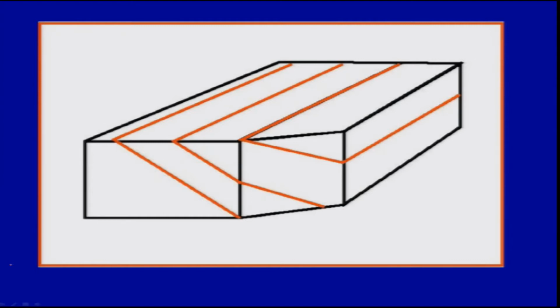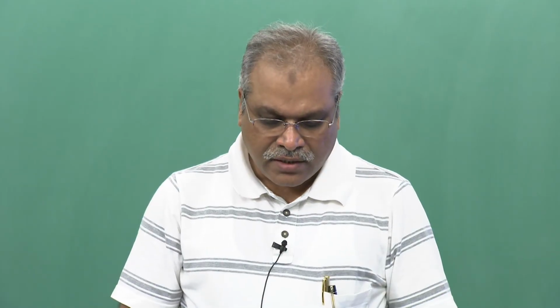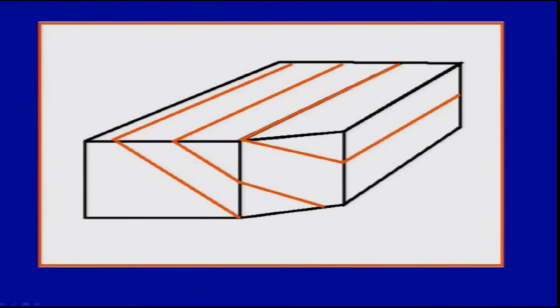If you come across any inclined or dipping strata or beds, it is extremely important to know and understand which face you are looking at, because that will determine whether you are measuring the true dip or the apparent dip. That is extremely important.